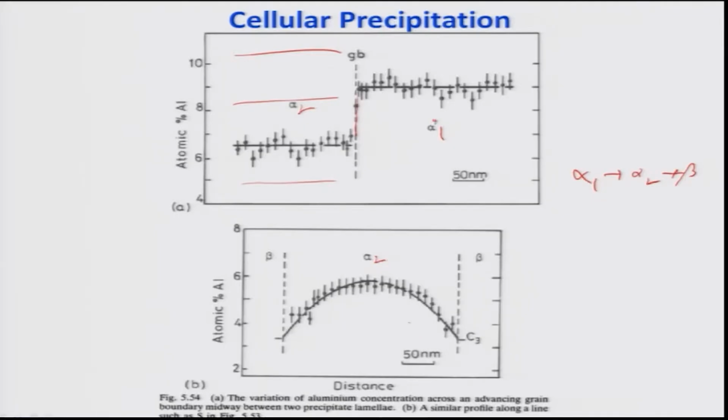This must exist, right. Obviously, at the tip of the grain boundary, the composition of the aluminum, or rather let me draw it and show you. So, this is alpha, beta, and then this is alpha, and then there is a beta, right, alpha 2. So, composition is like this. That means what? The solute has diffused from the tip of alpha, and this was the grain boundary, tip of alpha, along the grain boundary and reached here. This has to happen, otherwise how will the beta grow.